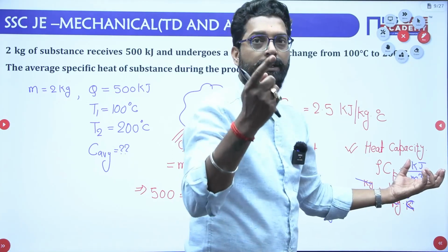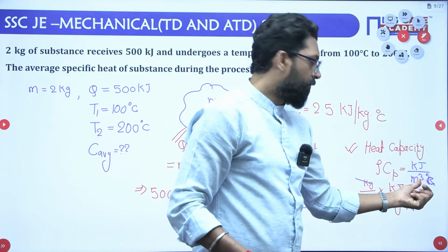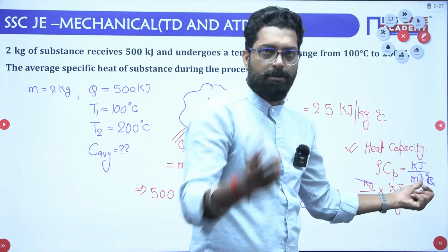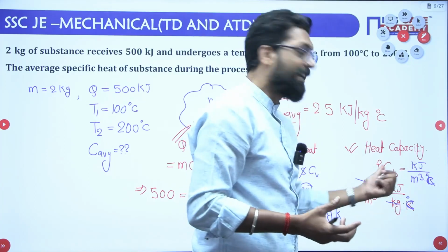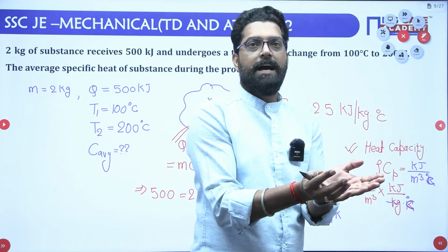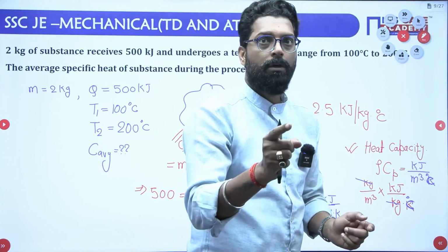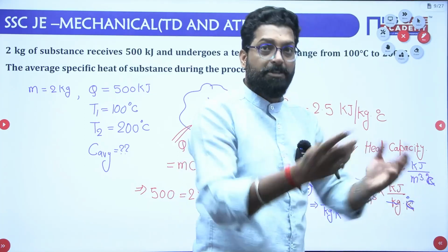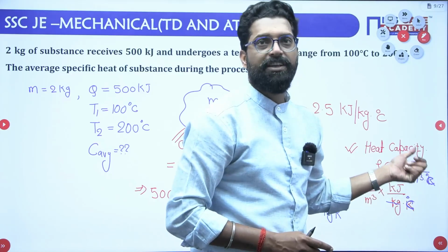That means what transfer? Diffusivity of heat. Diffusion of heat through a substance of 1 meter cube, let's suppose the volume is 1 meter cube. If there is a high heat capacity of the substance, the diffusion of heat, transfer of heat is low. If there is a low value of specific heat, the transfer of heat is more, the diffusion of heat more.